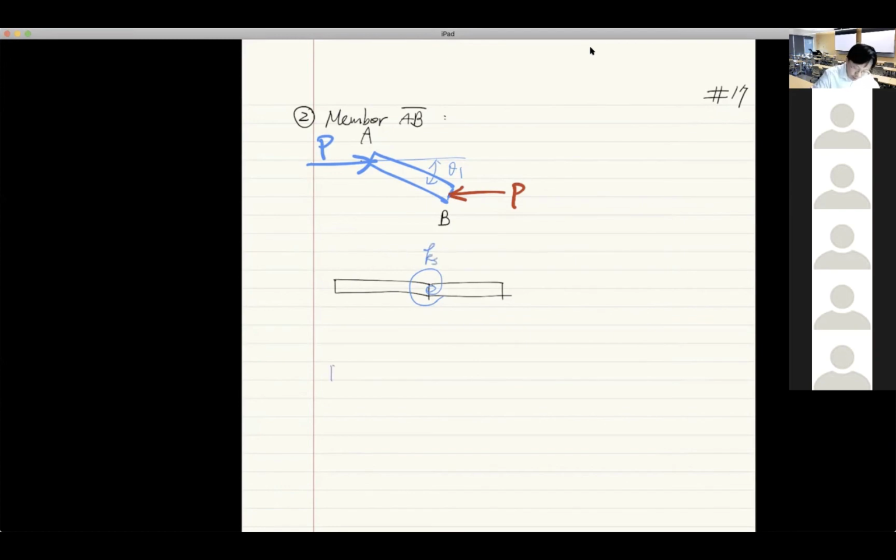But what if I bend it? What if I bend this member like this with an angle theta? So what is the amount of internal moment acting on these two members? And from here, we know that the internal moment must be acting in the direction against the motion, which means there's going to be an internal moment acting like this. And this moment equals the spring constant Ks times the angle of rotation, which is theta. Would you agree? Right?